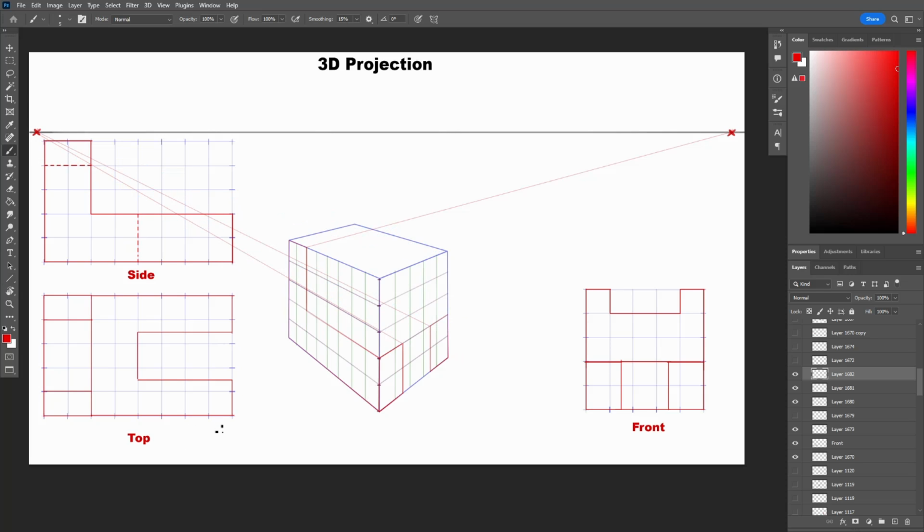the shape. The body of the object is 6 units long according to the top view, so at the 6th unit, we can project the lines all the way to the back as it is in the top view. Then, 2 units in, we can draw another line to end the space in between the 2 legs of the object. Finally, I can close the shape at the end and draw the end of the back side.